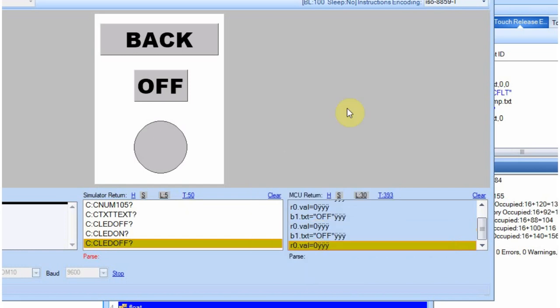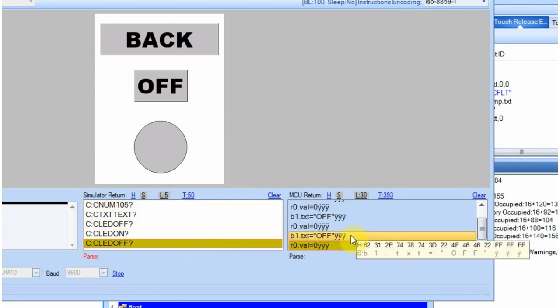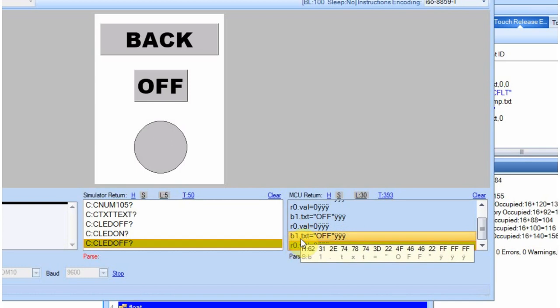So sometimes what you're going to want to do is you're going to have two serial ports on your laptop or your computer. And in my case, it's 10 and 11 right now. And then you can have the debug window going to a secondary serial port on your Arduino. Like in my case, I'm using serial 2 on pins 2 and 3 of the Nano. And then you have the regular Arduino port. And then you can see this activity down here on this debug screen. And that's really helpful because it lets you know what it is you're writing to.